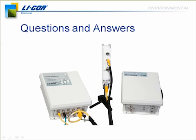And so we want to have an enclosed optic that allows for that. But at the same time, traditional closed path analyzers are going to require typically mainline power. They're going to require temperature controlled enclosures and other infrastructure that the LI-7200 doesn't. They're going to need long intake tubes that are going to attenuate your water vapor fluxes.